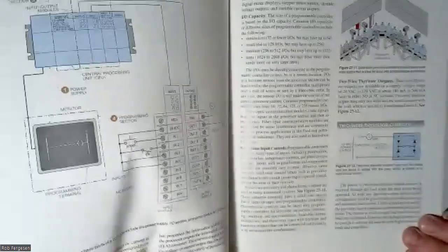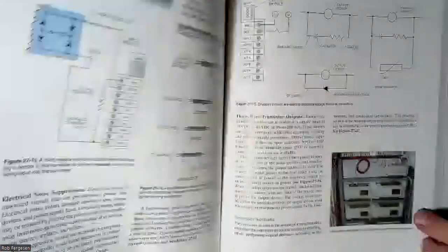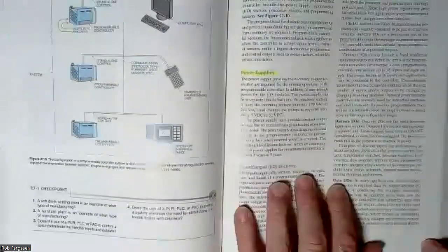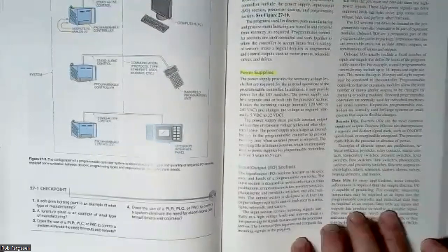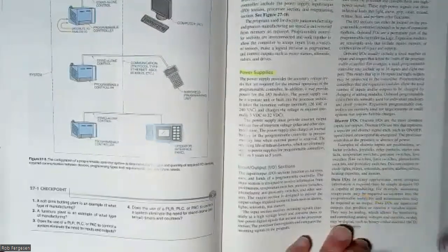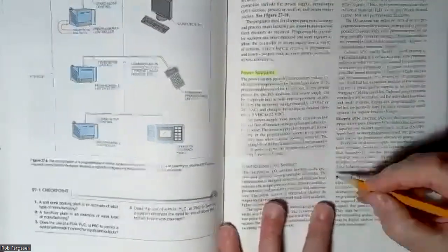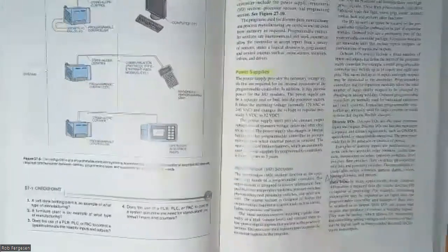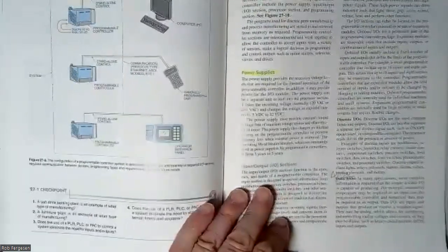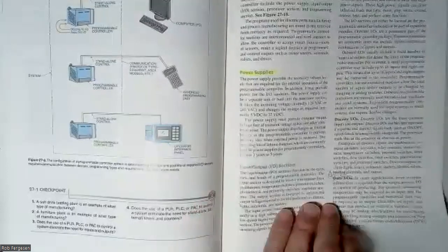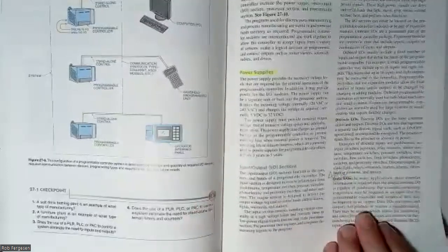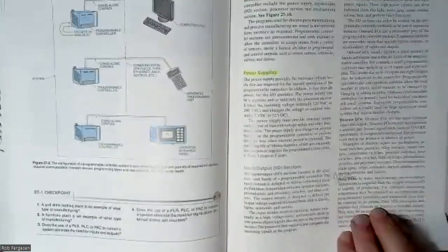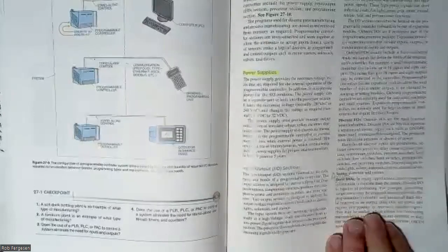Generally, I think they're making this a little bit vague. They call this data I/O. Most people call that analog I/O. So data I/O is probably not the best term to use. Typically, this is called analog I/O. So don't use data I/O if you want to sound smart to your PLC buddies. They're trying to, I guess, imply that there's other kinds of data besides analog inputs and outputs, which is true. There are specialized cards to communicate with other PLCs you can buy.